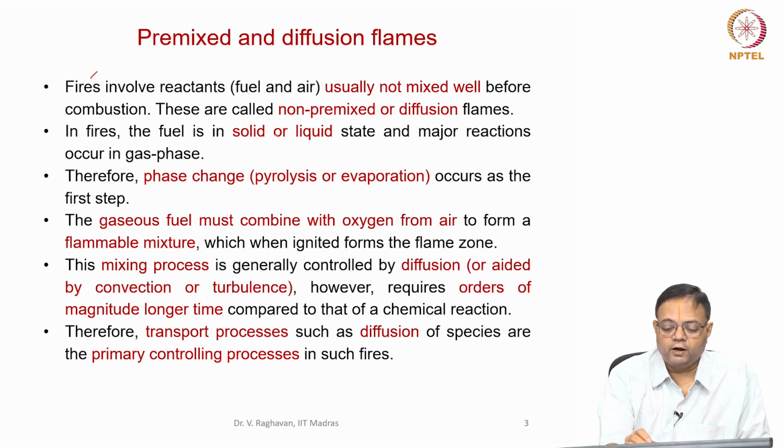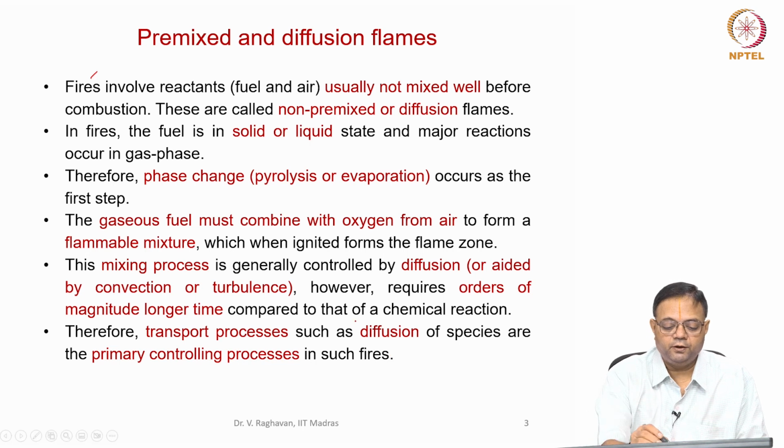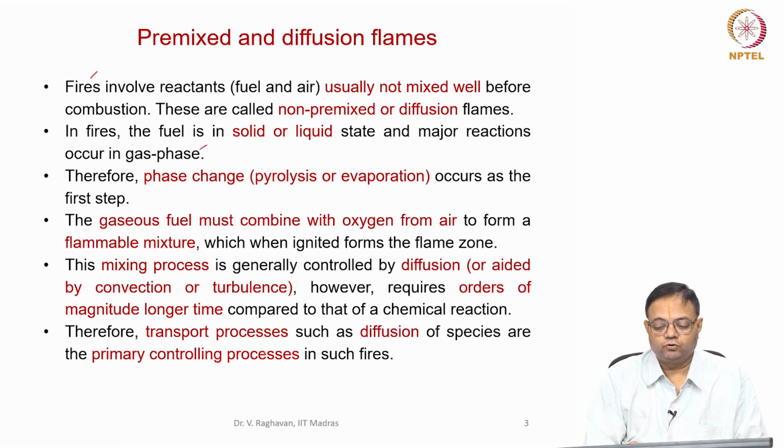If you take the solid and liquid state fuels, for example, you know that the major reactions take place in the gas phase, so the first step will be the gasification of these fuels, solid fuel or liquid fuel, to generate the gaseous fuels which will take part in the combustion reactions in the gas phase. So that means there is a limited chance that the premixing between the air and these vapors will occur. Due to which these are non-premixed flames.